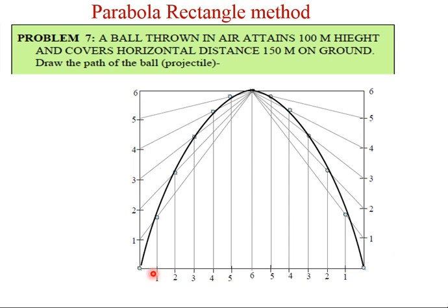How many equal parts? 1, 2, 3, 4, 5 and 6 equal parts. In a similar way we have to divide this EF into the same 6 equal parts.